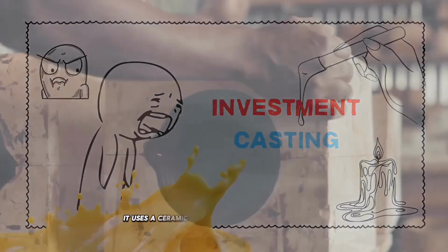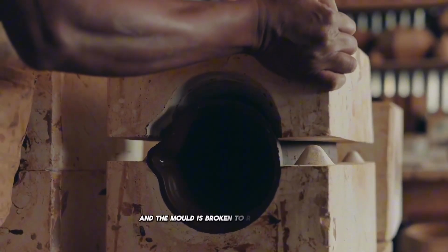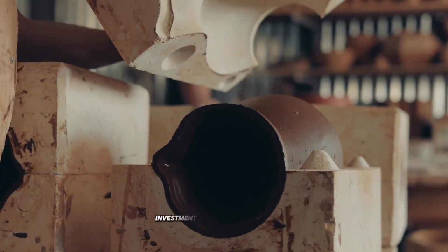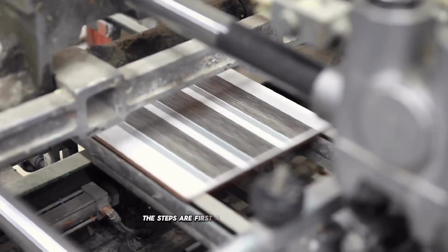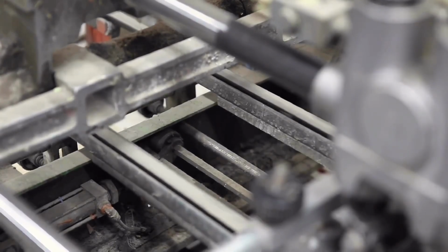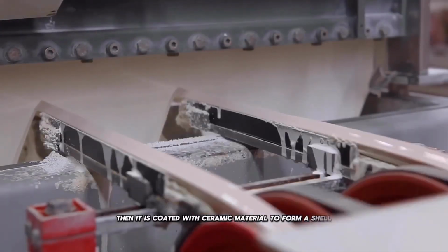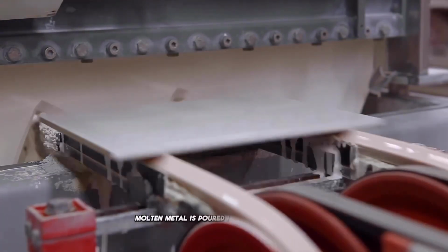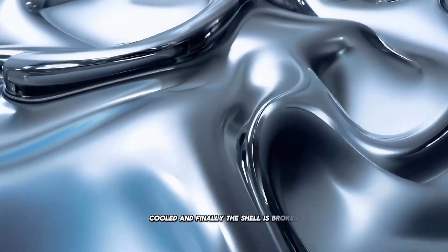It uses a ceramic mold made around a wax pattern, and the mold is broken to remove the part, so it cannot be reused. Investment casting is highly precise, but the process is time-consuming. The steps are: first, a wax model is created, then it is coated with ceramic material to form a shell. The wax is melted away, molten metal is poured into the ceramic shell, cooled, and finally the shell is broken.